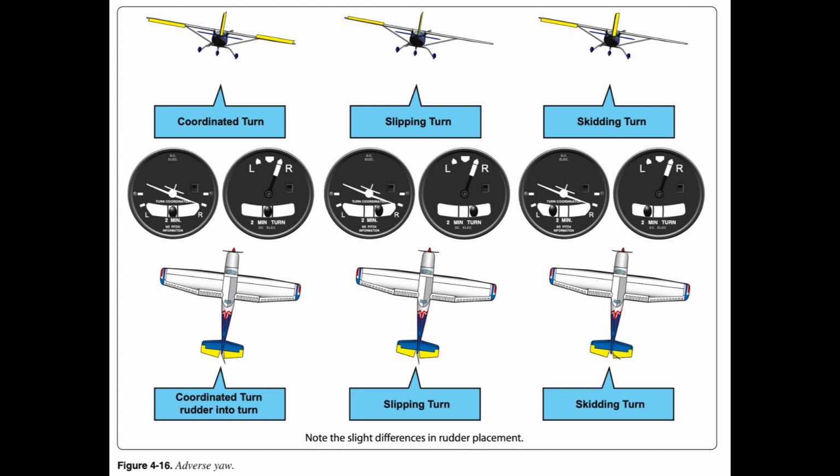Types of icing. Structural icing. Structural icing refers to the accumulation of ice on the exterior of the aircraft. Ice forms on aircraft structures and surfaces when supercooled droplets impinge on them and freeze. Small and/or narrow objects are the best collectors of droplets and ice up most rapidly. This is why a small protuberance within sight of the pilot can be used as an ice evidence probe. It is generally one of the first parts of the airplane on which an appreciable amount of ice forms. An aircraft's tailplane is a better collector than its wings, because the tailplane presents a thinner surface to the airstream.